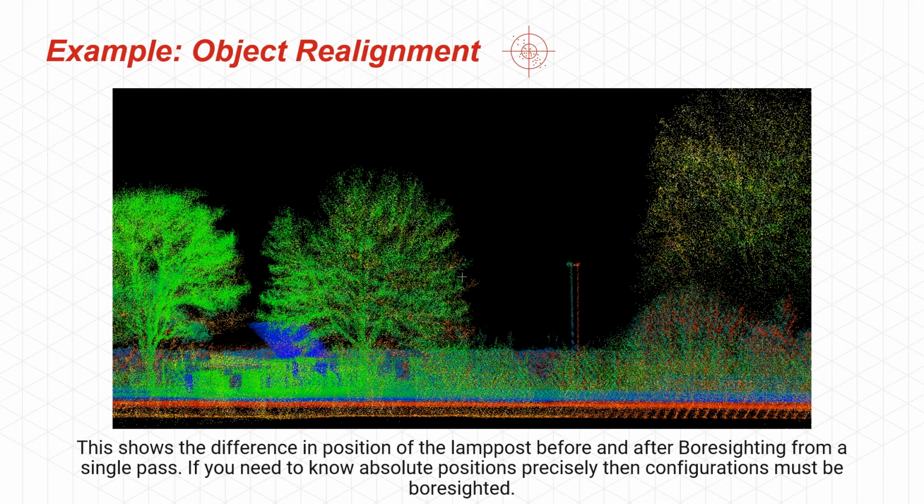As you can see here, there's about a meter difference between this boresighted solution, which would be the reference, and the non-boresighted. So if you're surveying objects some tens of meters away, they're going to be in the wrong position by some meters. And that's obviously, if you're caring about absolute accuracy, something you want to account for.